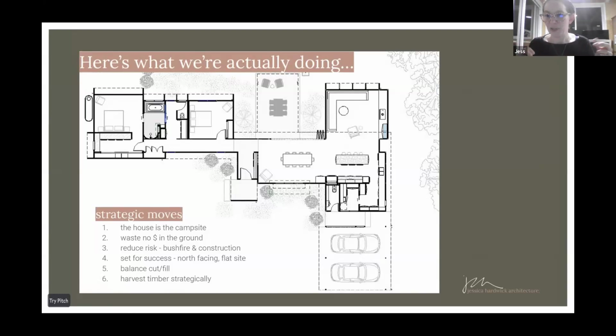When we say a thin plan, we're just meaning that we're not double or triple loading rooms from north to south. By having ideally a long, thin building that faces north in the subtropics, it means that as long as you have nice overhangs on that northern edge, you're going to get really deep sun coming into those spaces and onto the masonry surface of the floor, if it is masonry. In our case, it is.